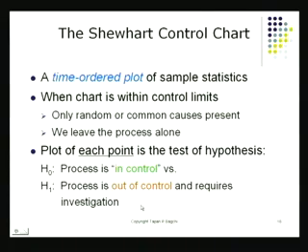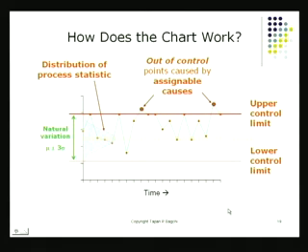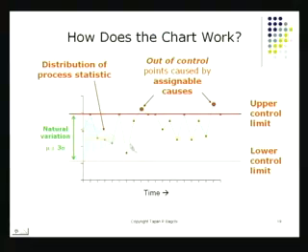So I've got these two situations. I've got something called the process is in control, which is the base case, and the exceptional case is the process is out of control. These two I figured out by looking at the actual chart itself. So here is an example. I plotted the chart. I might have plotted the x bar value for various samples that have come along, and I notice the upper and lower control limits. These control limits have been marked, and I'll show you the formulas for these. There are some special formulas that are utilized to calculate the upper control limit and the lower control limit. Once these are known, I can plot the data.